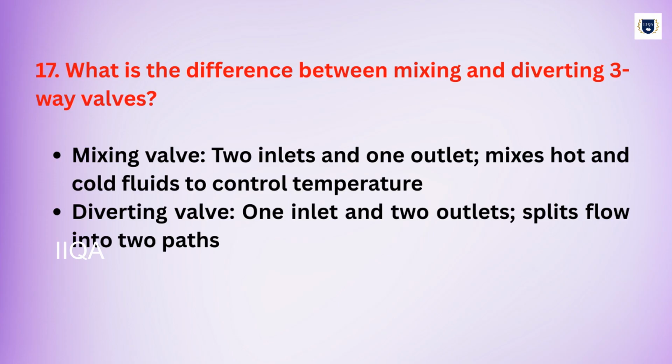What is the difference between mixing and diverting three-way valves? Mixing valve: two inlets and one outlet, mixes hot and cold fluids to control temperature. Diverting valve: one inlet and two outlets, splits flow into two paths.